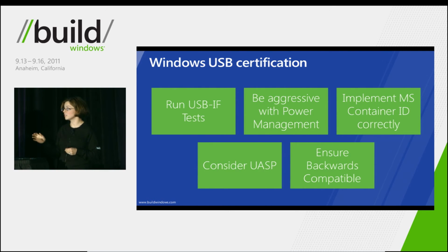Also, there are selective suspend and function suspend requirements. Especially for internally attached devices, all of them are required to support selective suspend to allow better power consumption for the system as a whole. If you do have a multifunction device, then you need to implement Microsoft OS Container ID. And there's lots of information available about it because it's the feature that we had since Windows 7.